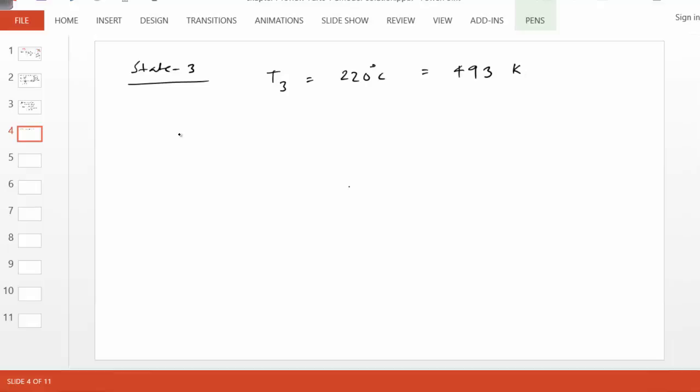So therefore, the actual turbine output is m dot times h1 minus h3. Recall, m dot h1 is the energy carried by the flow into the turbine, and m dot h3 is the energy that is leaving the turbine in an actual turbine. And so that becomes m dot cp times T1 minus T3 for the PG model. Again, from handout J you can figure that out. It's written under the PG model, these formulas.